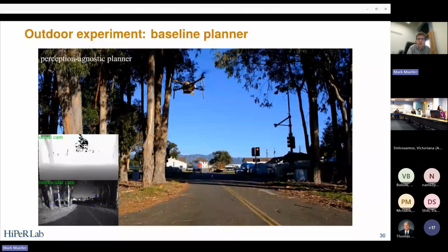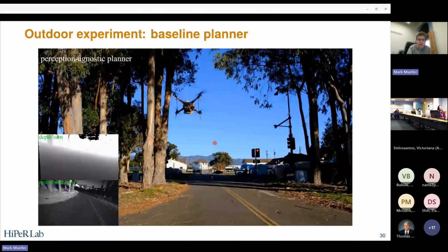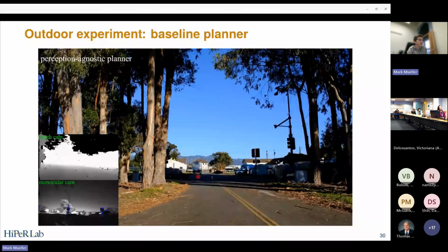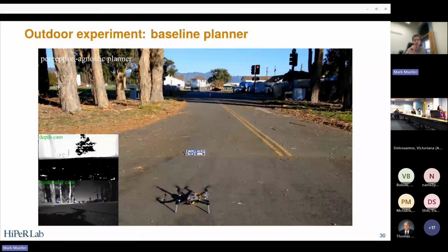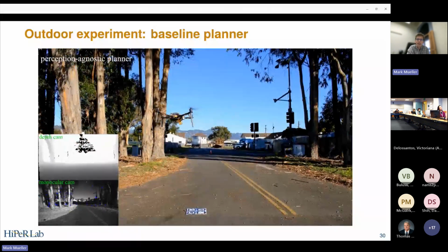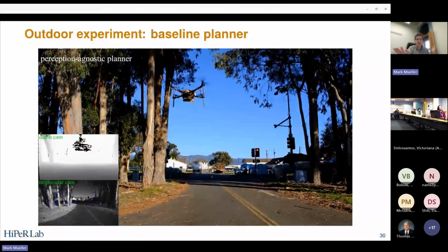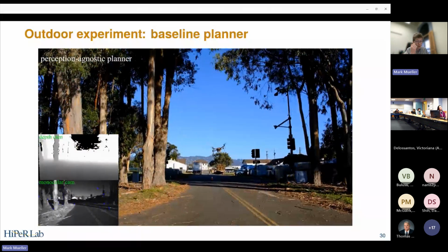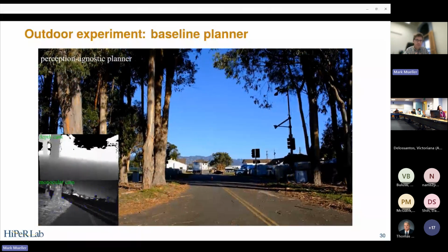Because there are no obstacles, it can fly more or less a straight path just from point A to point B. Now, it's not perfectly straight. You see the vehicle sort of maneuver slightly to the left and the right, and that's just because of the random sampling, right? So sometimes, the random samples will be slightly to the left or to the right. And of course, it makes sense. If you ask me to fly through empty space from point A to point B, I'm going to try and fly a more or less straight line to do that.